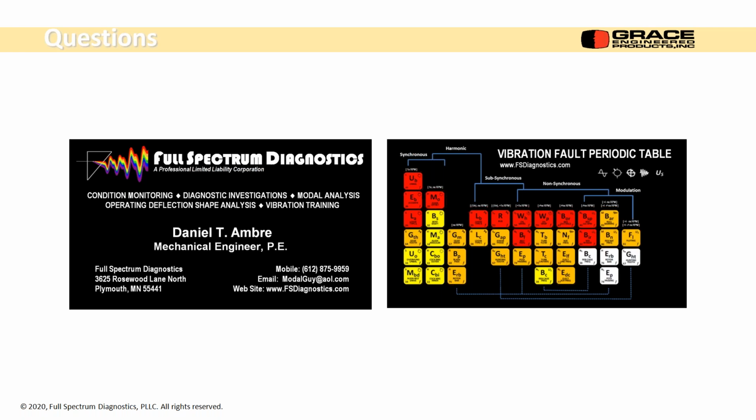But the other thing is, if you're changing speed and you have a natural frequency close to or in that range, you can amplify the natural frequency and have other problems. Those are the big drawbacks. If you're route based, you'll usually set the VFD to a value, 60 or 40 or 50, whatever you normally run at, and you'll lock it in and take your data at that frequency. Now you have consistent data throughout the year, but you might be missing something due to that speed change. That's the real limiting factor.